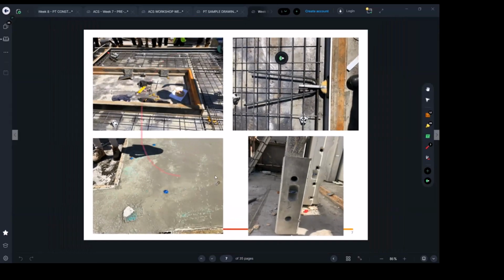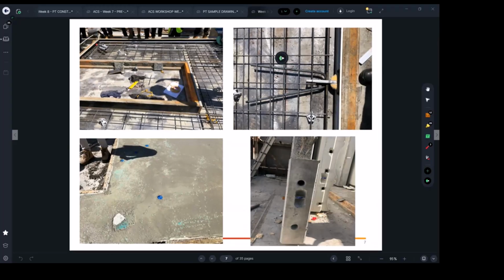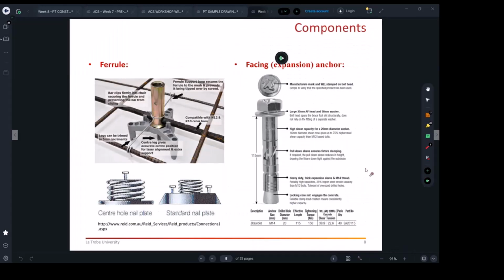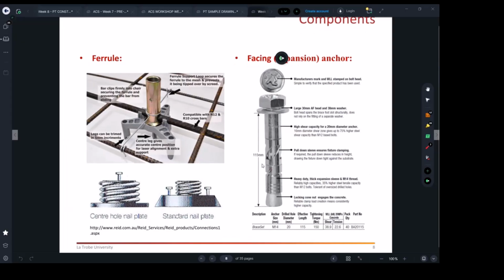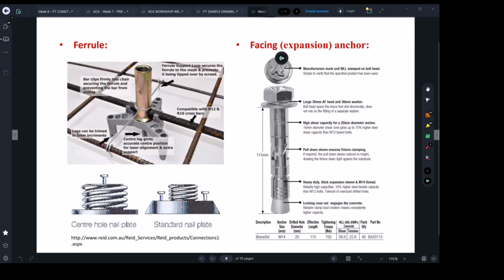All right, so these are just some real pictures taken of panels during the construction process and after it. Again, this image is talking about the ferrules, which as I told you before, can have different functions. One of them is fixing the props into your panel, and another is that you can be face-lifting the panel by using them.